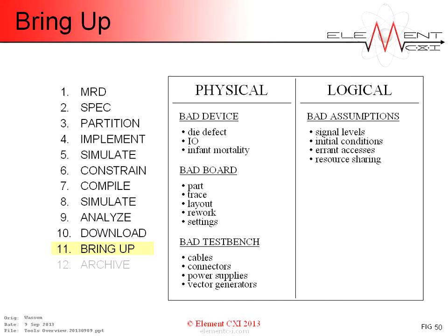Resource sharing conflicts with misbehaving IP. Misinterpreted data characteristics, format, precision, boundaries. Unanticipated data stream behavior, packet size, count, intervals, jitter, and protocol violations like unsupported features, or worse, improper implementations.